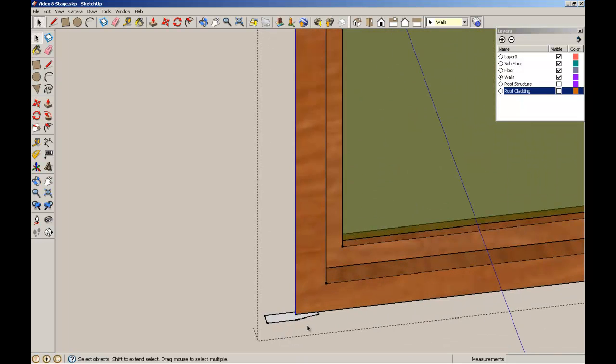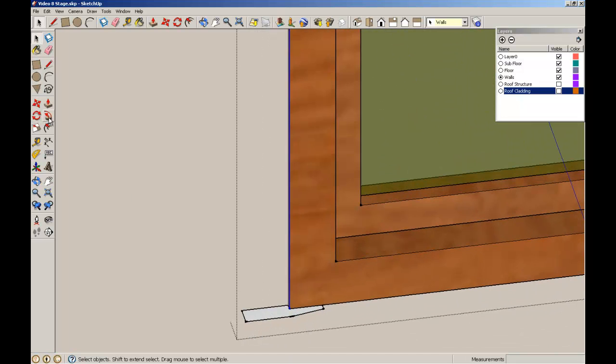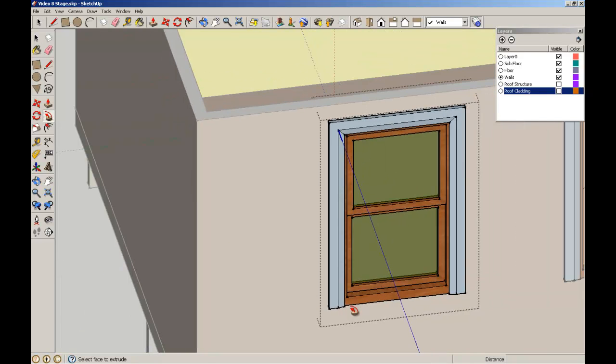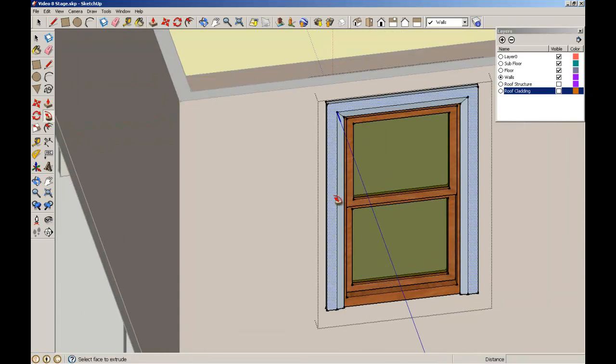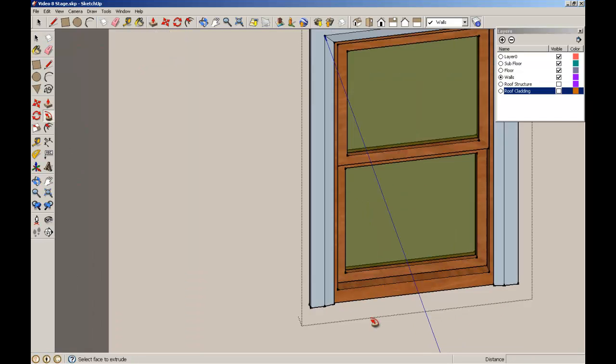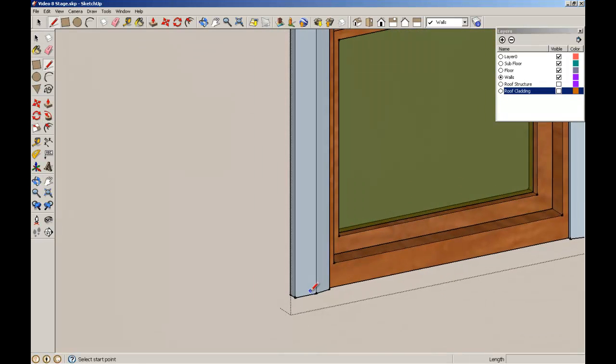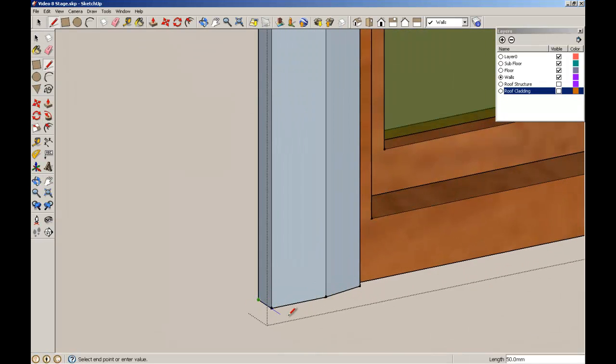I'm going to just zoom in a little bit to my extrusion. I'm going to use the Follow Me tool. Now, because I've predefined the path, it should work a little easier. As soon as I select this, the lines will disappear, but then I'll select the surface and fingers crossed, it should work. So there you see. What it's done is that it's interpreted my path very clearly and brought that element all the way around that perimeter of the window.